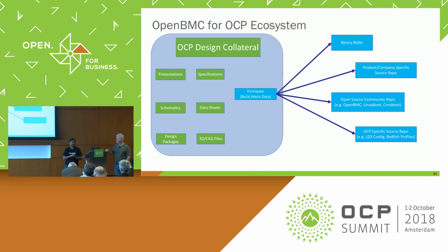Also it doesn't have all the security features, like verified boot kind of features. So what we did was work with Portwell, one company who make these COM Express boards. They have offered a commercial version of a development board for OpenBMC. It looks like a BMC board, but it has a COM Express where you can plug in any COM board onto that. That way you have a complete server environment where you can test all the features. And we added TPM, dual SPI flash, so that we can verify verified boot for the BMCs, and TPM for the BIOS, and TPM for the host. So that's the closest I can think of at the moment.